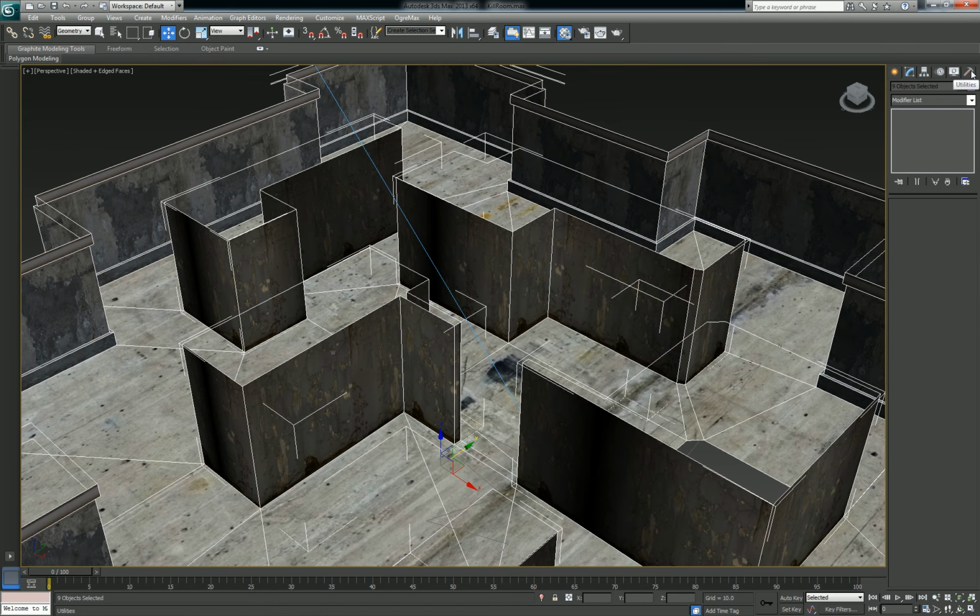That's this little hammer in the top corner. I'm going to select that, and I'm going to reset everything, reset selected. So this will force all my geometry to that 1 unit equals 1 inch scaling necessary for this map to behave properly once we get into the engine.